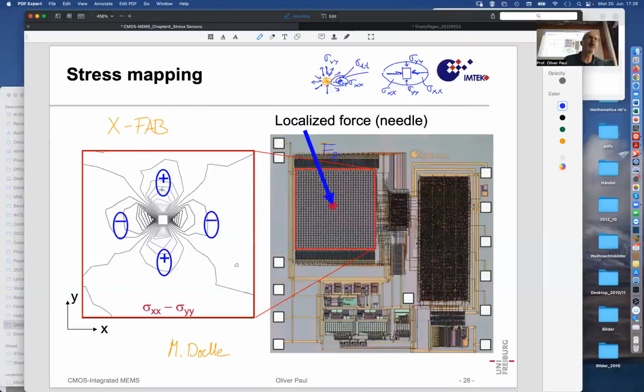If we look at the top, sigma xx minus sigma yy has now the opposite sign, because the role of x is taken over by yy. This is now the component that has the large direction here. Like this pair of arrows, we have this pair of arrows here, and then we have the smaller perpendicular compression, which is now the tangential direction here, which is the x direction. So x and y have switched order, and therefore the sign has changed, and that is exactly what is measured.